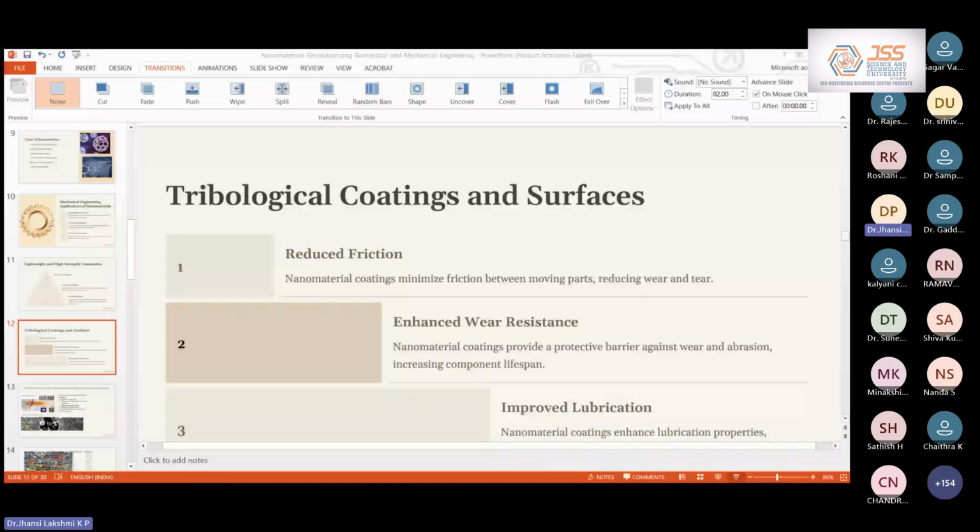Here, the B4C particle concentration is varied. The hardness of the bare sample, that is the plain substrate, is also checked. With 0% B4C particle concentration, we are maintaining 80% alloy powder as the matrix and 20% reinforcement.